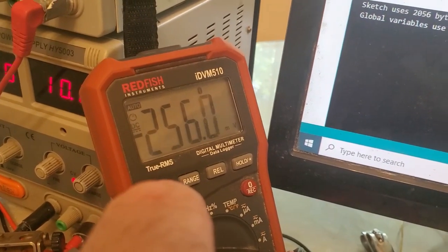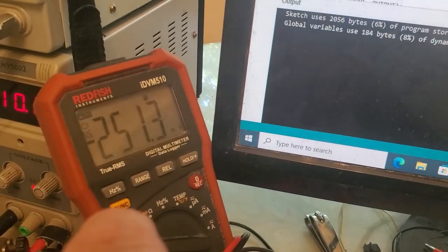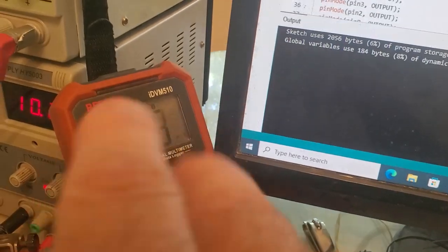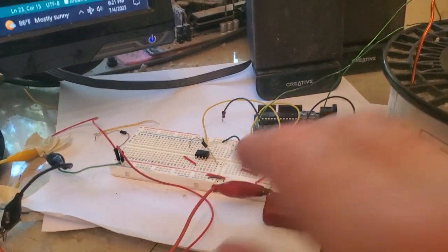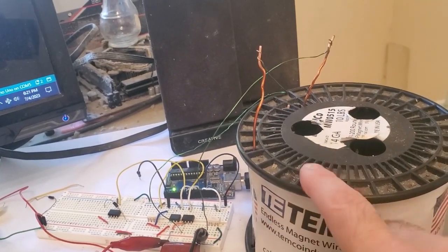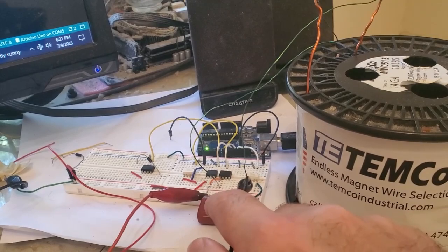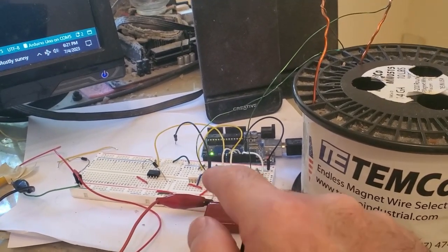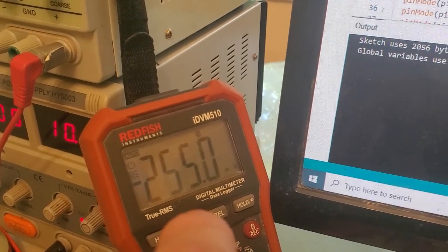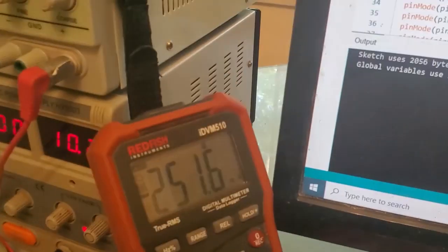It could be something with components that's changing and is nonlinear, especially I'm thinking the timing of the switch, whether it's fast enough, or the other possibility is there's nonlinearity both in how this thing is charging, the tau time of the coil, and then you have the tau time of the cap, the RC constant. So there might be an interaction there, but it's close. So it's a little more than halved. It's just about going to 0.